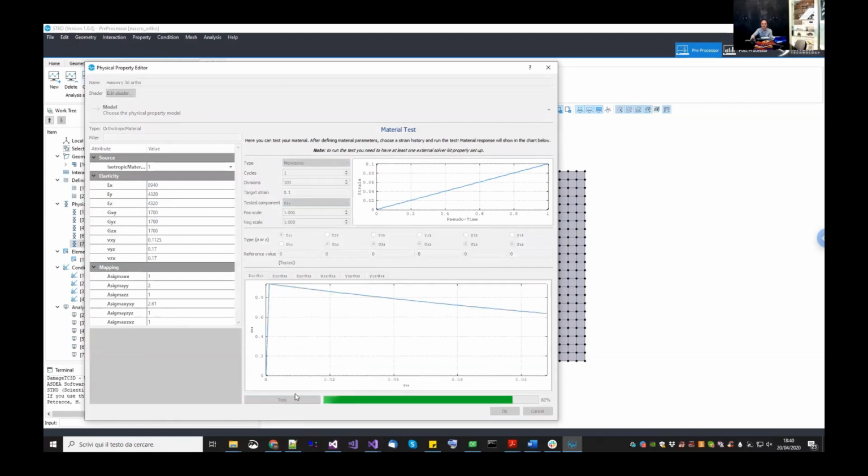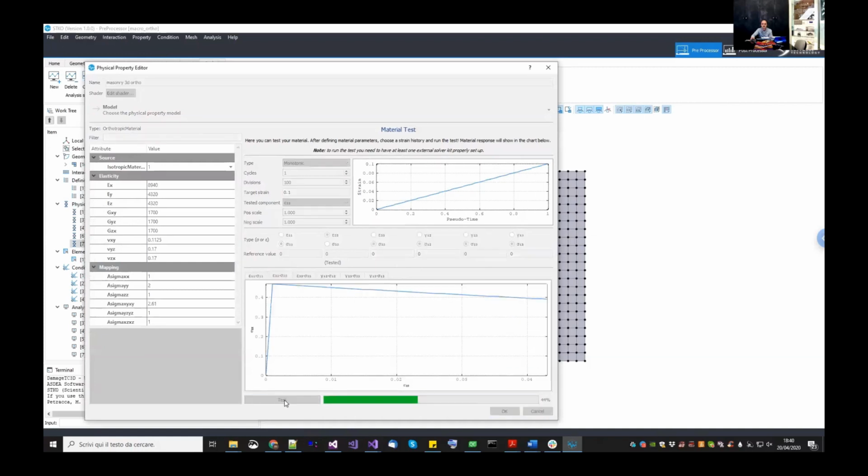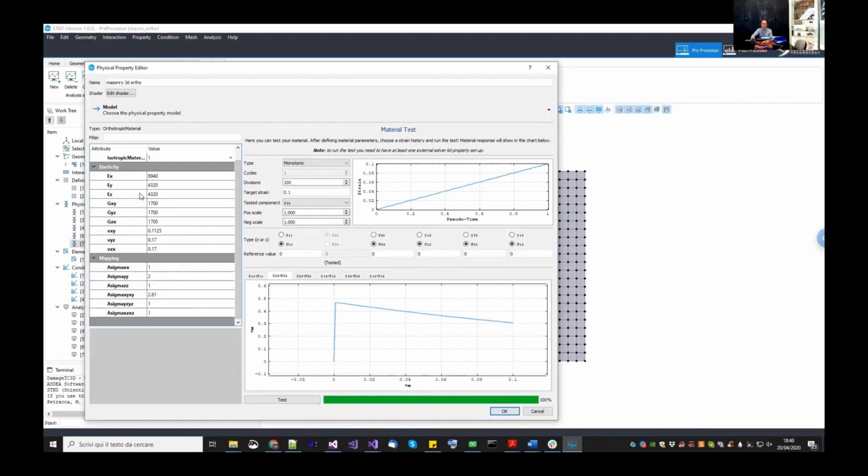But what I want to show you is that in X, you have the same thing we have seen before, 0.9. And now if I do the same along the Y direction, it should be 0.45 more or less, because the factor is 2 here. So let's see what happens in the second direction. Oops, I set 0.22, which is fine. Okay, 0.45, which is exactly the value that we decided before. And the same happens in compression and shear.